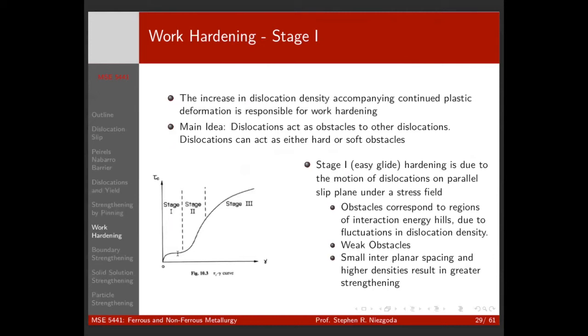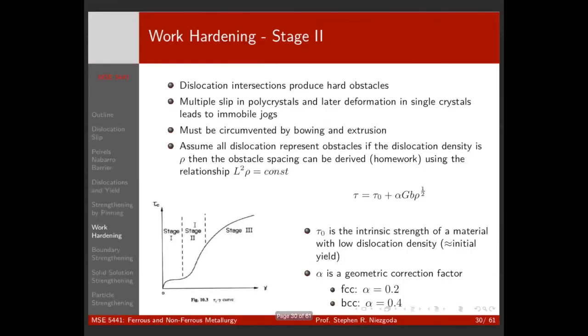The dislocations, once they get moving, are just free to keep running because they're not hitting anything else, except maybe some grain boundaries. Well, it's a single crystal, so they're not even hitting grain boundaries, right? But they're not interacting with other defects.